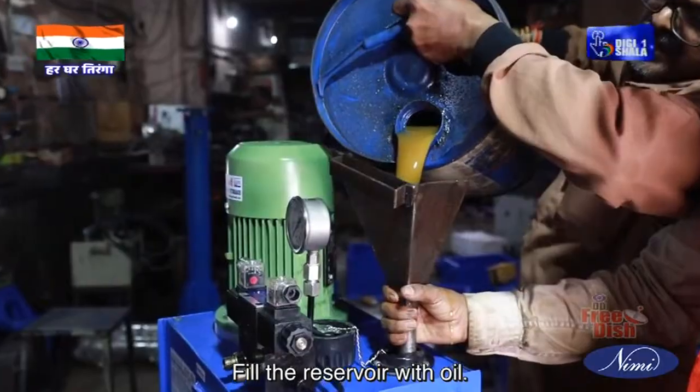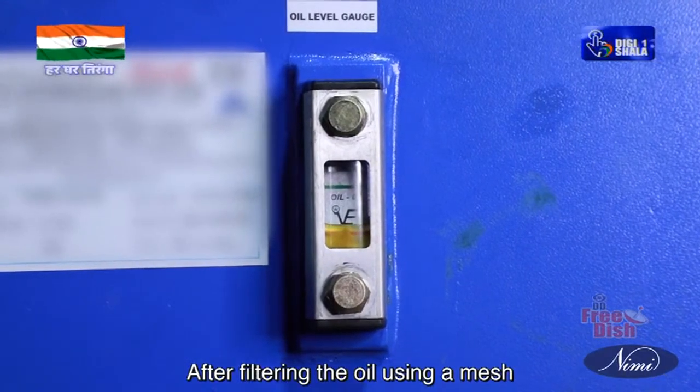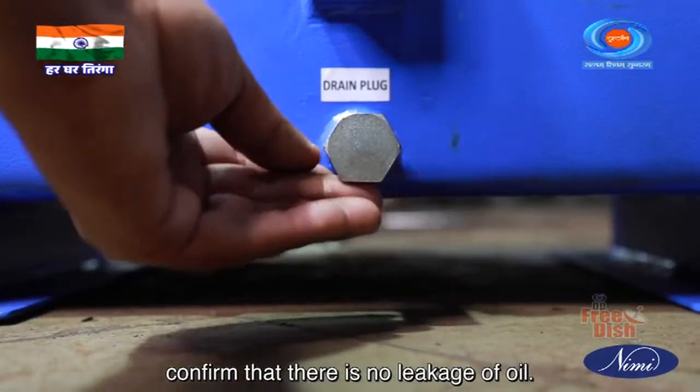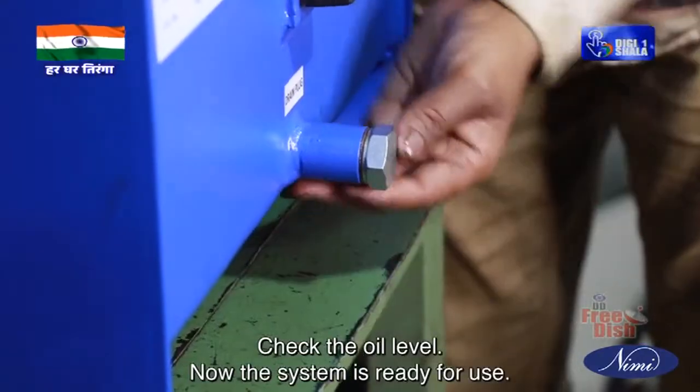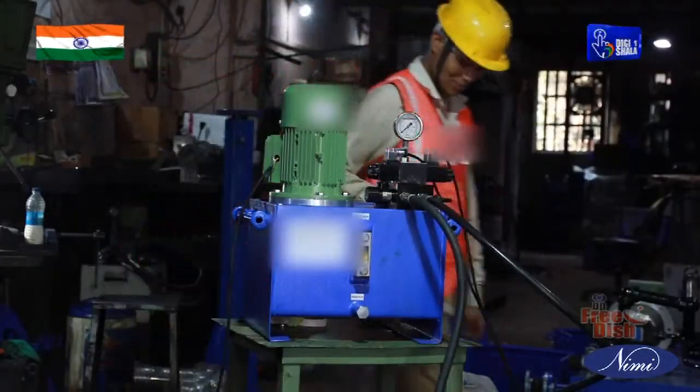Fill the reservoir with oil. After filtering the oil using a mesh, confirm that there is no leakage of oil. Check the oil level. Now, the system is ready for use.